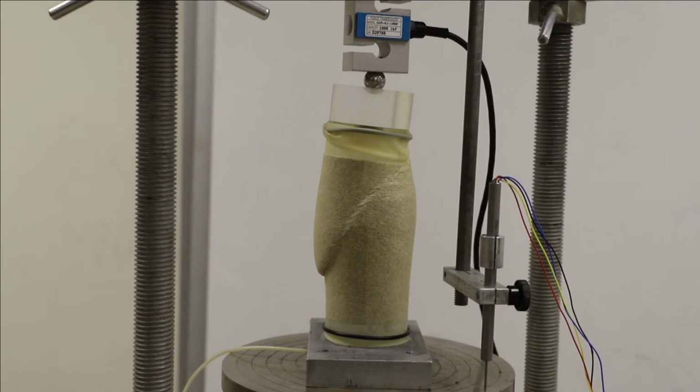And of course, if it's the loosest, it's going to be the weakest, and so that soil continues to shear, may continue to dilate as you get out to large strains. So this is a really great example of localization, shear plane failure in a dense granular material.